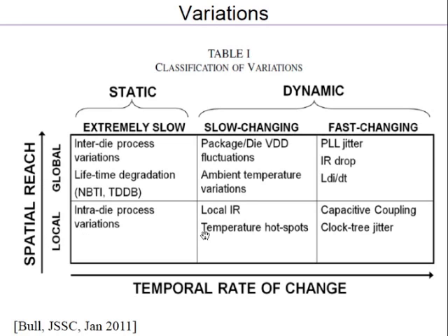So we said intra-die process variation. Local: the voltage is not uniform for all the gates. Every gate will see a slightly different supply value depending on where it is in the power grid. Temperature could be different across the chip, and you can have very fast changes. These are changes where the clock period itself, TC itself, changes.